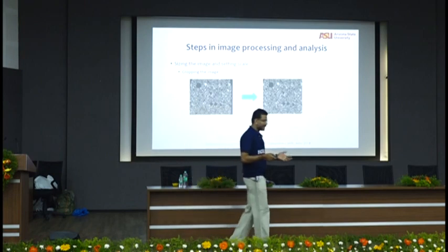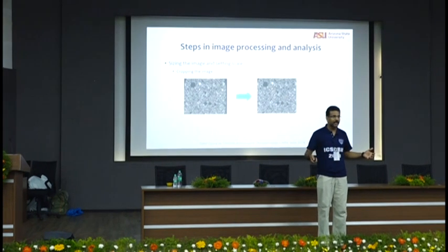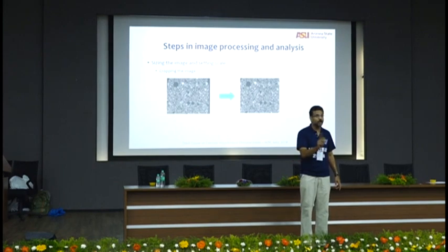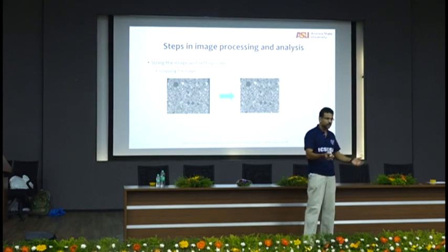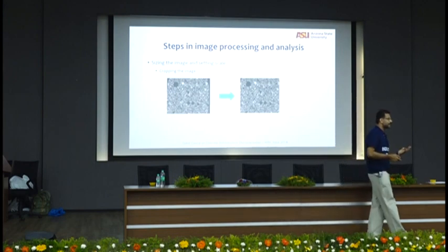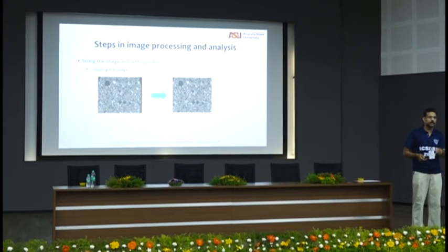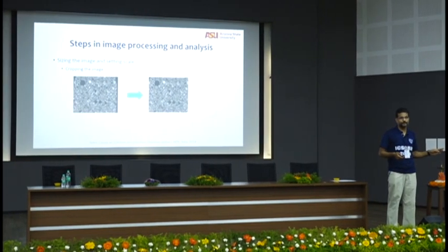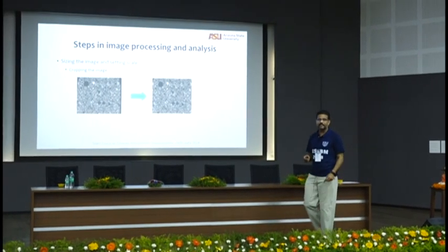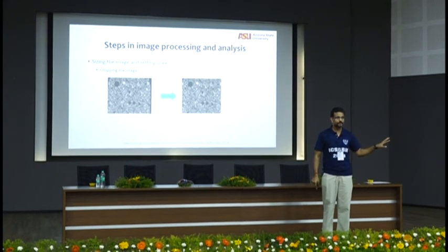So you cannot do image analysis on a 30,000 zoom SEM and try to quantify. If you zoom to 30,000, your only intention is to find out what that is, not how much there is. You should do this on low magnification images so that you get a representative area. If your cement grain is maximum 50 micron in size, you have to have at least a 500 micron image to do any analysis. Otherwise, you're not doing the right analysis. If in that 500 micron image, one accidental 100 micron particle came in, throw out that image. You cannot use that.